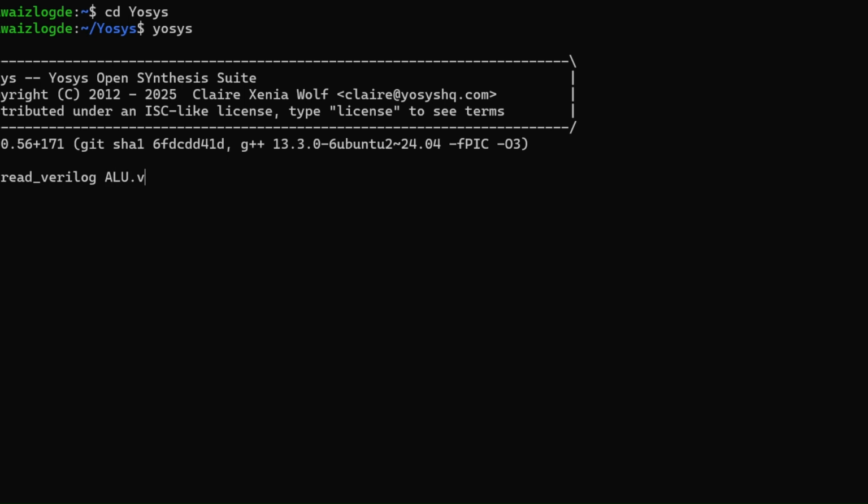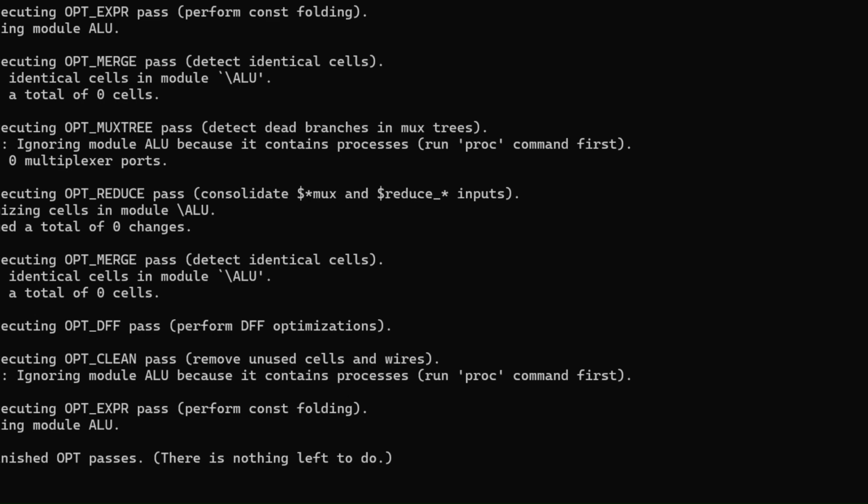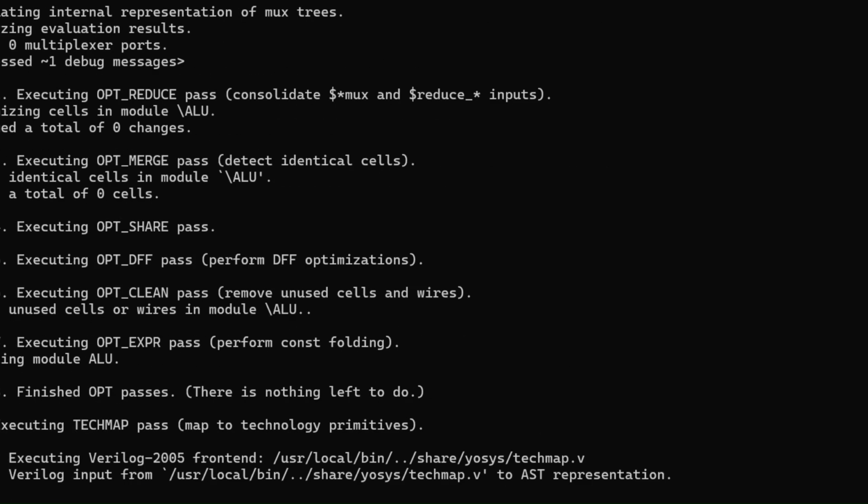In parsing, the tool reads and interprets the RTL code. It checks the syntax of the RTL code. It expands the modules, resolves parameters, unrolls generate blocks, and many such things. It tries to convert the behavioral code which we have written into a Boolean expression. So the tool does not just read it, it understands the meaning and builds an internal data model of regs, wires and operators.